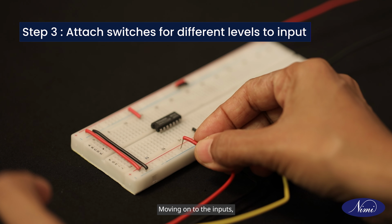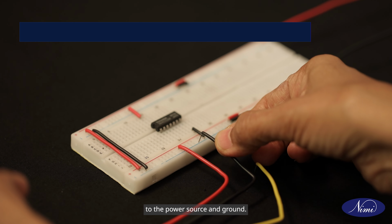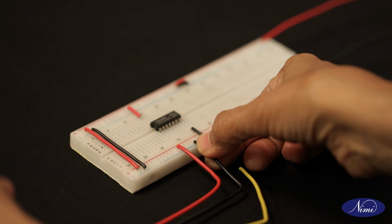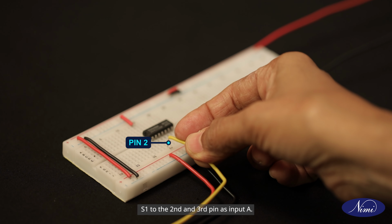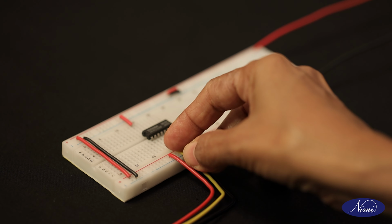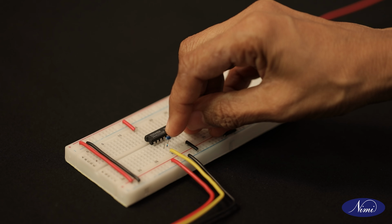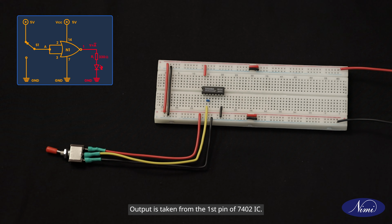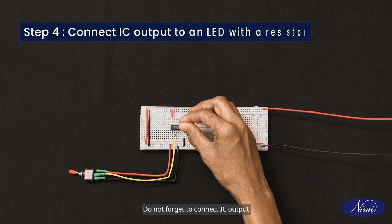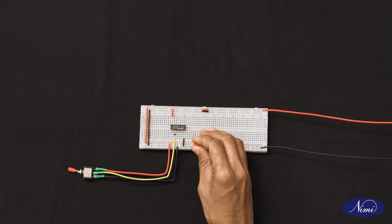Moving on to the inputs. Connect both terminals of the toggle switches to the power source and ground. And connect switch S1 to the second and third pin as input A. Output is taken from the first pin of 7402 IC. Do not forget to connect IC output to an LED with a resistor.